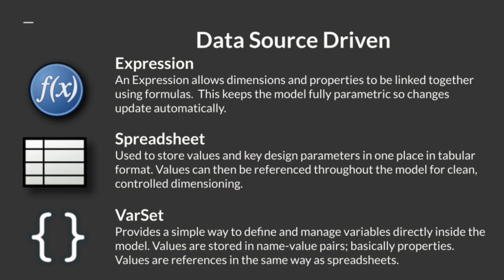Instead of hard-coding numbers directly into sketches, it's often helpful to drive dimensions using expressions, spreadsheets, or varsets. This approach reduces direct dependencies between features, making the model more flexible and easier to modify. If a key dimension changes, updates will automatically propagate without breaking the downstream features.